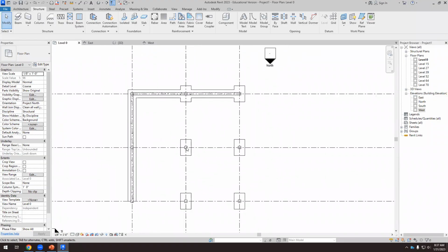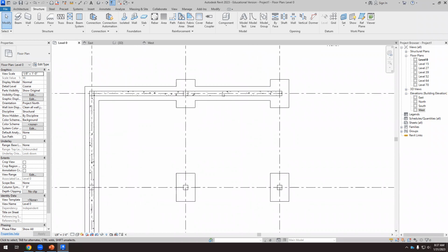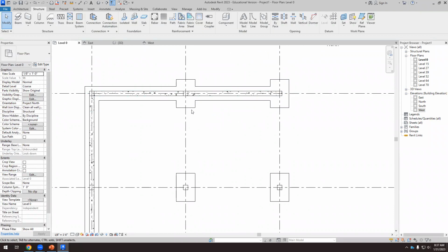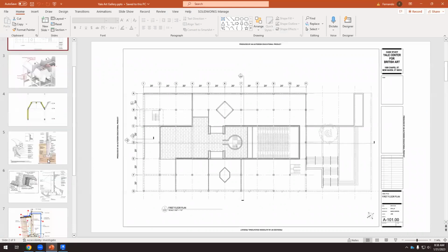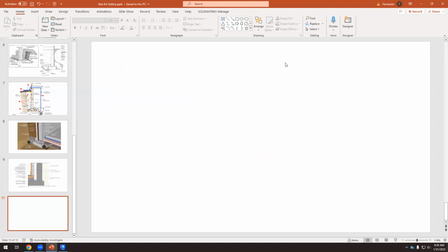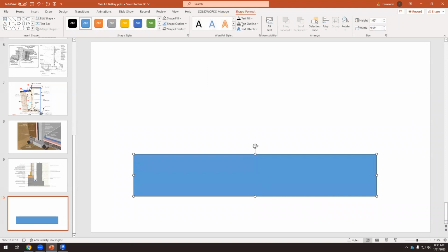Okay, so I am inserting here the footings. So we have the wall, we have a column embedded here. We have the wall footing, we have the isolated footings. So sometimes we need to reinforce the footings where we have the wall. So what does it mean? Okay, if we have a wall in the basement, so that's the wall. For the wall, I'm going to need a footing.